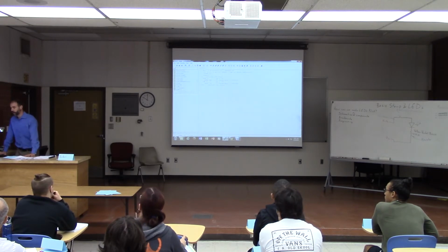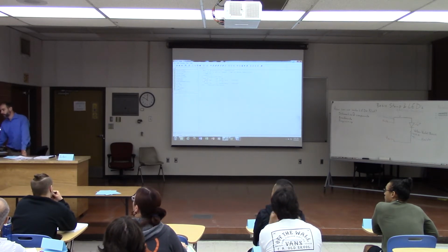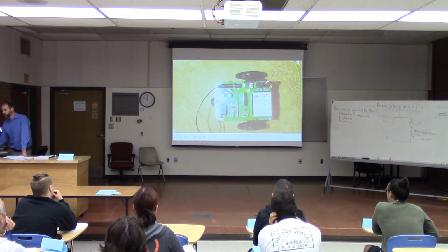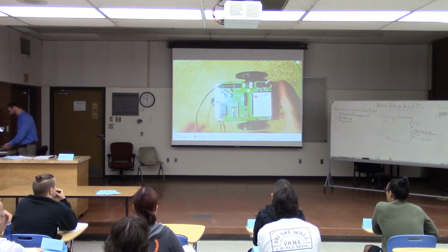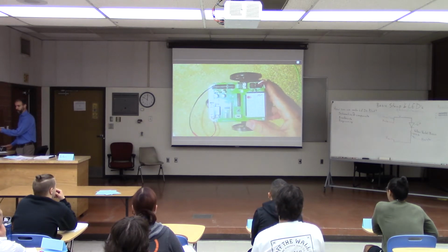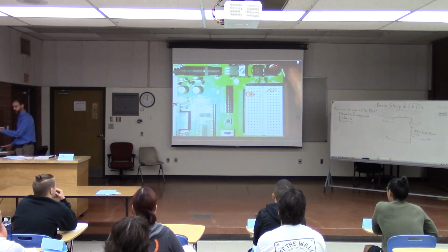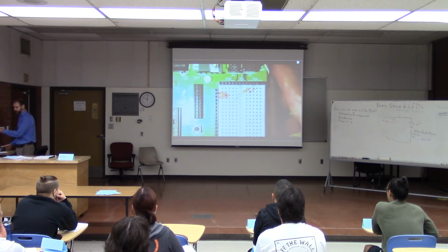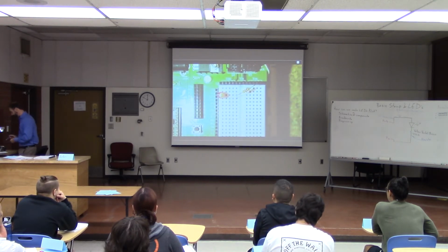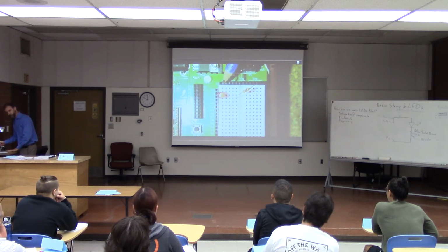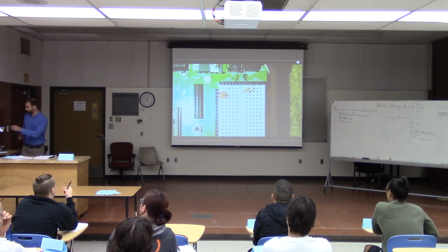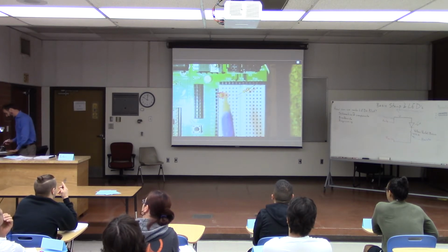Phil asked about the change that we actually made to the board itself and how we connected the LED differently. So before, remember, the anode of the LED was connected to VDD. So before, the anode was connected to one of these holes up here. Now the anode has been moved over to this hole right there.